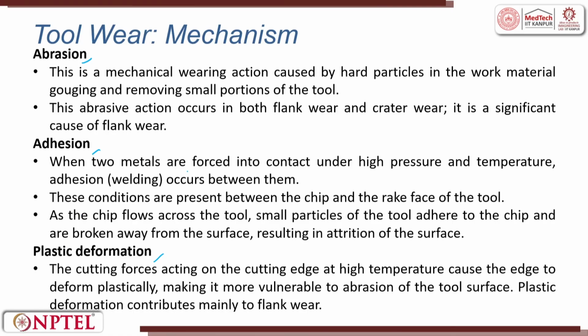Adhesion is when there is a very high temperature between the chip and the tool, a thermal affinity happens and there is a diffusion happening. Because of this, there is wear. When two metals are forced in contact with high pressure and temperature, adhesion occurs. These conditions are present between the chip and the rake face. Plastic deformation is because of the very high temperature: when the chip moves, softening happens at the tool, which leads to plastic deformation.